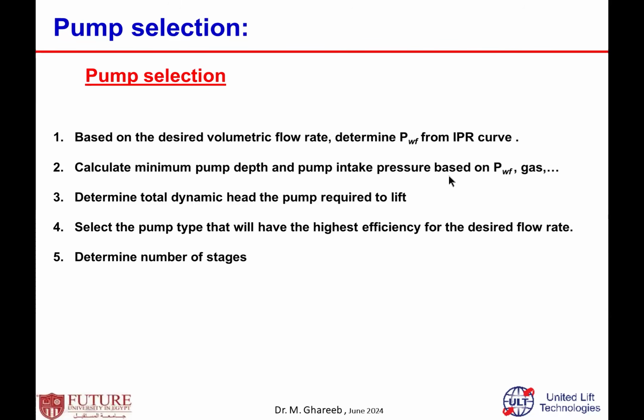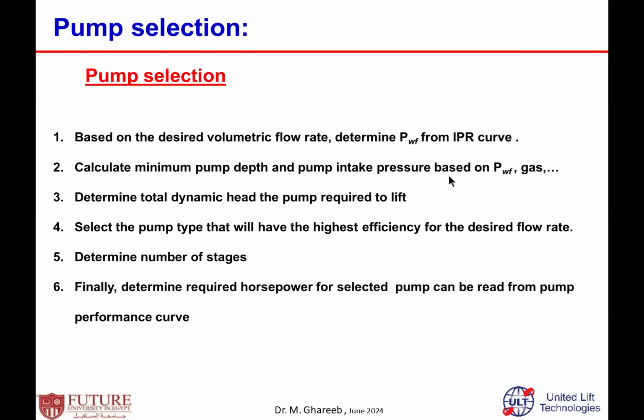how many stages are required for this pump in order to lift the fluid and overcome all the friction loss and all the dynamic head. After that, you need to calculate the horsepower required: the horsepower for the motor to run this pump, to rotate the intake, to rotate the seal, and so on. Then the total horsepower, the cable size, and the voltage drop in the cable, and so on.